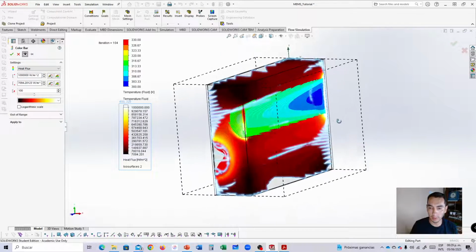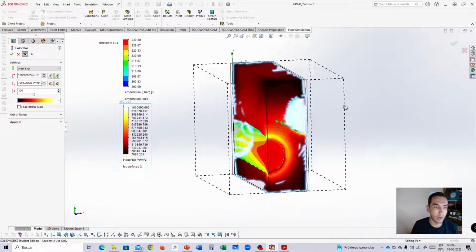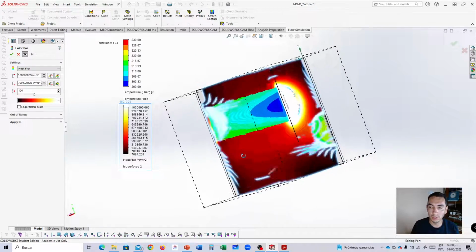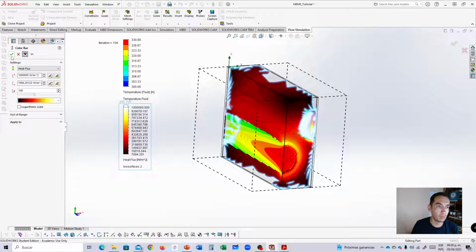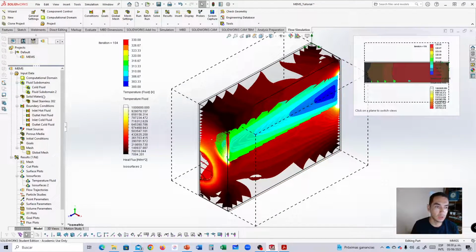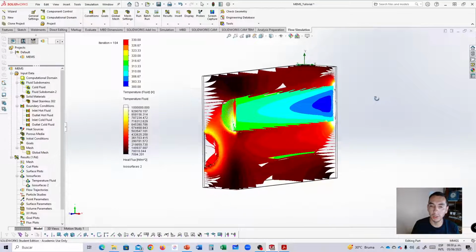and now we have a better visualization here. So the darker color means lower heat flux, and the lighter colors mean a higher heat flux that occurs in the entrance part of the tubes. So I'm going to click OK. So I'm going to deactivate the computational domain, and now we have something like this. The jet color table is going to be for the temperature, and the thermal color table is going to be for the heat flux.